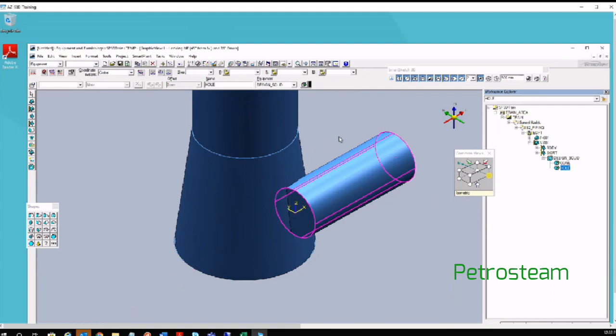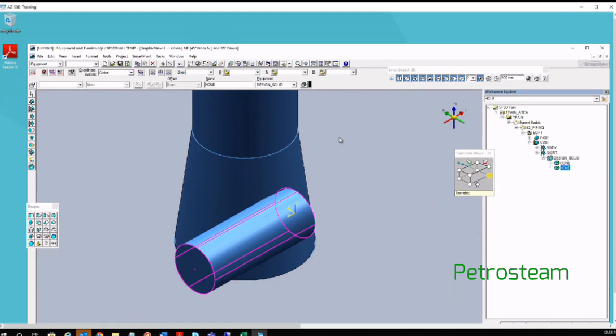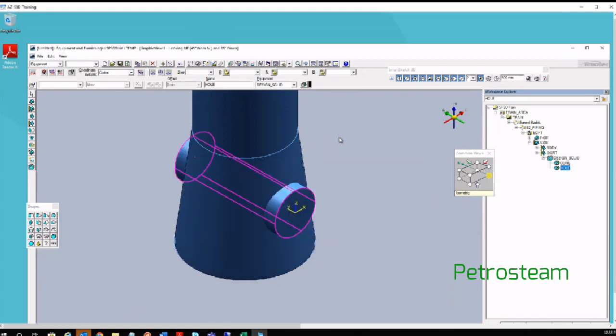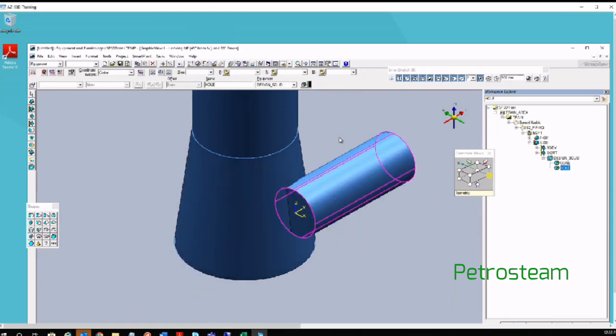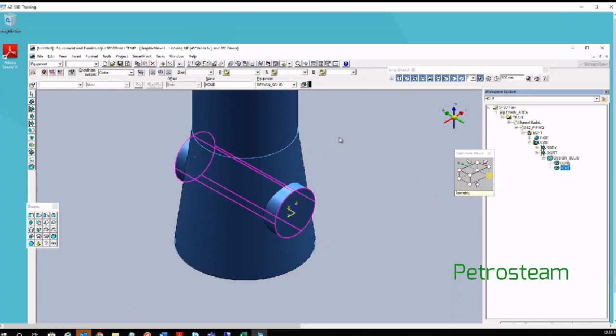Similar to earlier, use the up arrow key to activate the Z axis. After that, I will use the right arrow key to rotate it. So the Z axis is visible. Around that, it is rotating by 90 degrees, 90, 90.